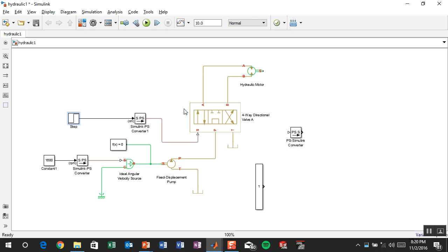And all of that, as far as valve design, just goes back to how they make the spool and how they make the ports. So it's really neat, because you can capture, hey, I know my spool weighs this much, and I know my spring constants centering the spool are this much, and you can figure out what natural frequencies of the spool would mess you up. We can really dig in, and that's this whole balance. The first day we talked about fidelity versus efficiency of modeling. You can dig way down if you care about it, and I'm hoping we can get away with not doing that for this, just because of time.